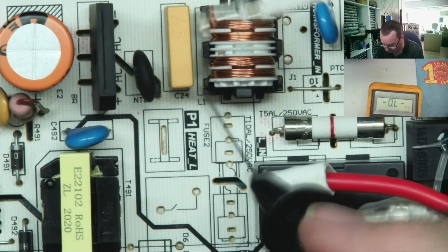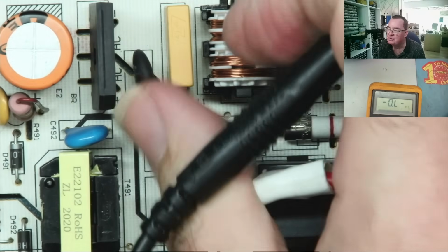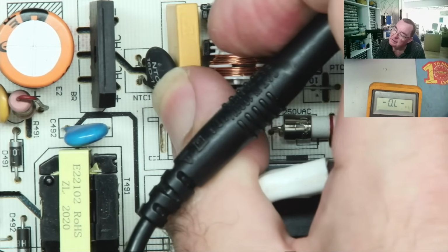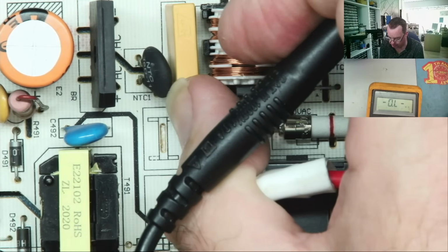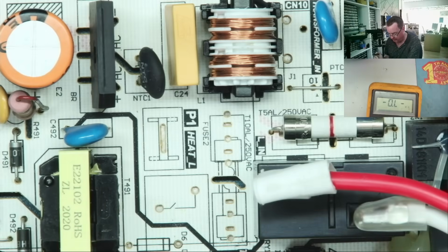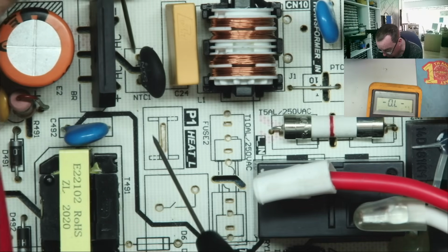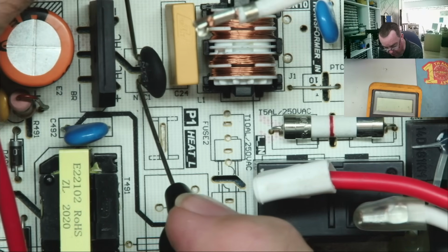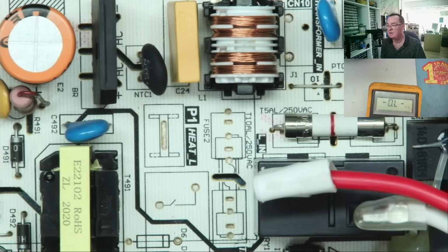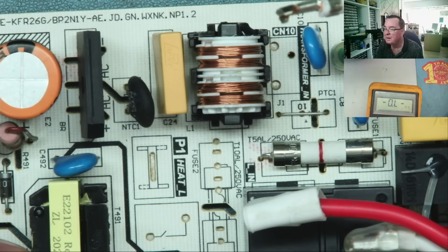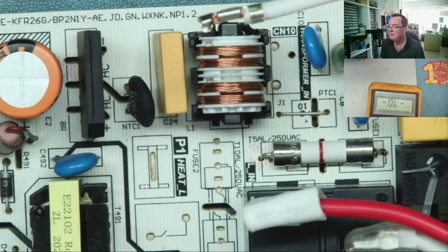Oh, but there is one more, that's this NTC, so this should read very low really. 16D11 you can look up, but this is going to be a low value. It's to stop too much current when you switch on. The inrush current reads 18, I'm quite happy with that. If they fail, they blow up usually, burn up, and that's because something else is short. So that's all the resistors I can see on the top side of the board.